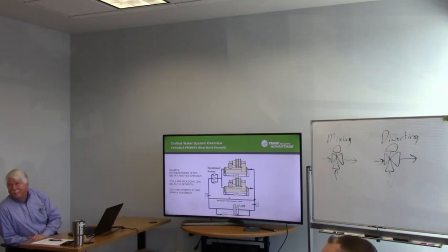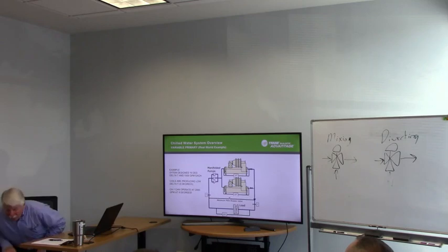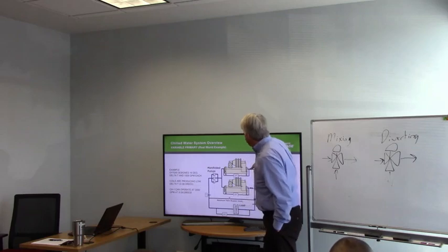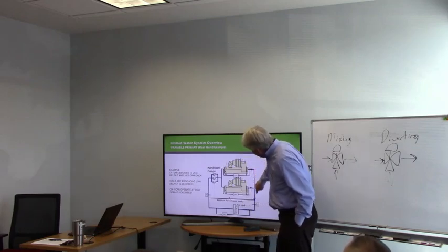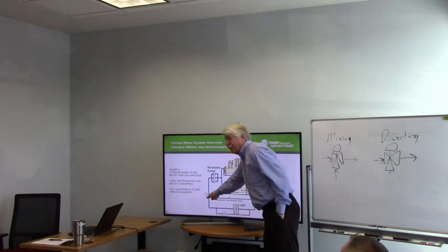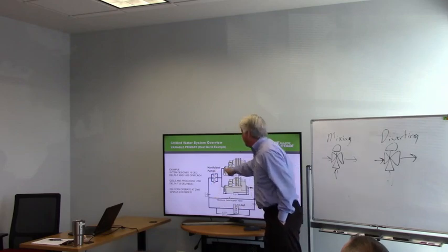Where do you get 8 degrees from? I just made it up. It's like 8 degrees in the system, correct? Yeah, 8 degrees for the chiller. For the chiller. Okay. In other words, what I'm saying here is, this chiller is designed at 1,000 GPM, it leaves, goes out here at 42 and comes back at 58, 16 degrees. So that's what it's designed for.